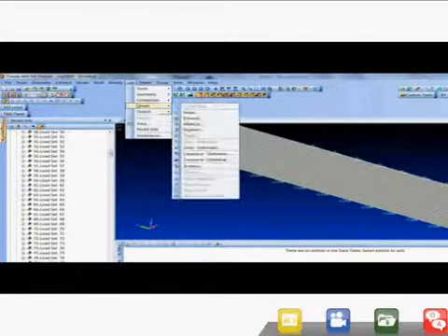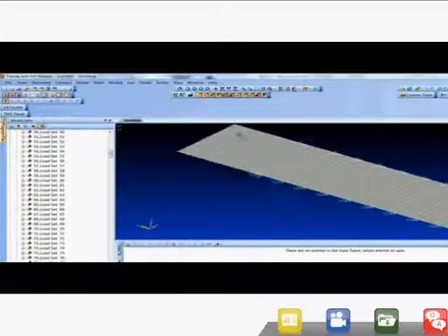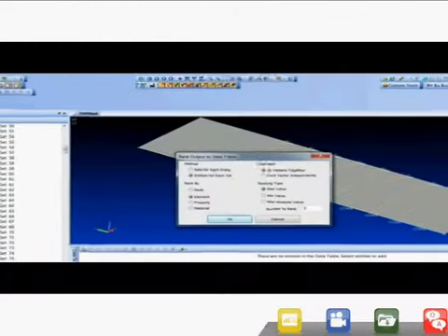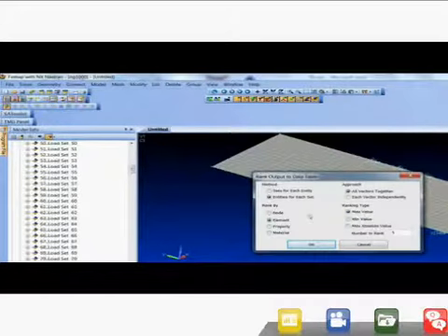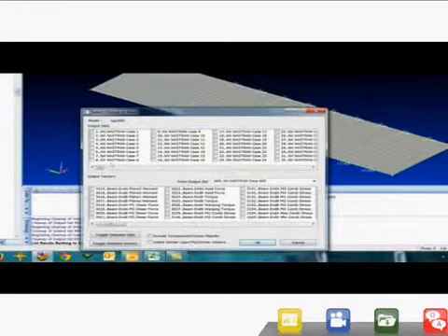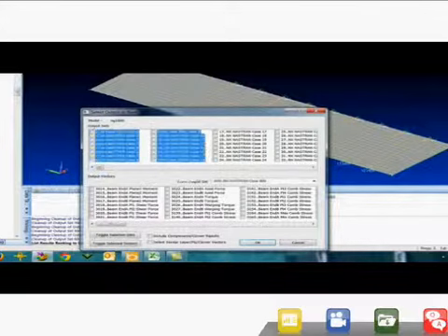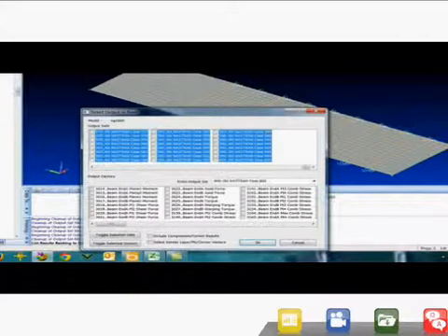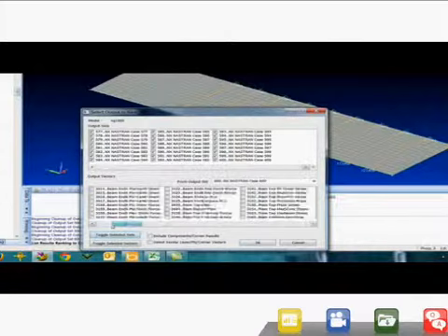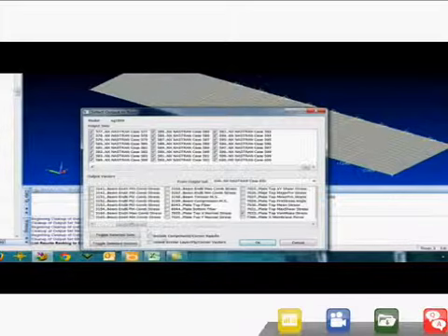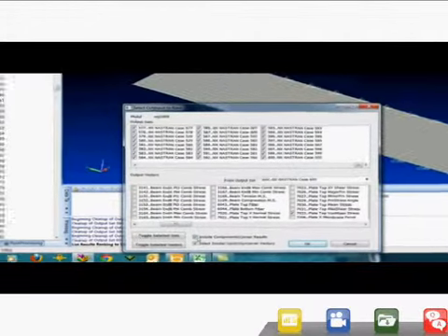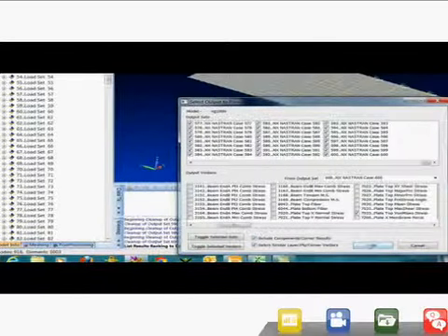We have this list output results ranking to data table. And I'll just take the defaults here, and there's some options in here depending on how you want to do this, but we're just going to grab the top 5 max value. You can multi-select. Here's all my 600 output sets. I can just box pick across them and toggle them all on. And then come down here in my output vectors and find top von Mises stresses. And then include similar. So this will go get bottom von Mises, and I'll get the corners too.